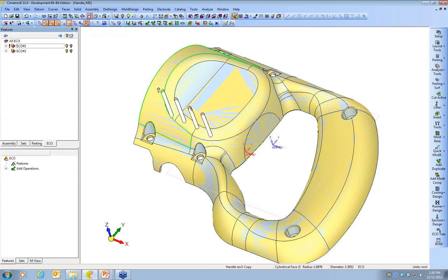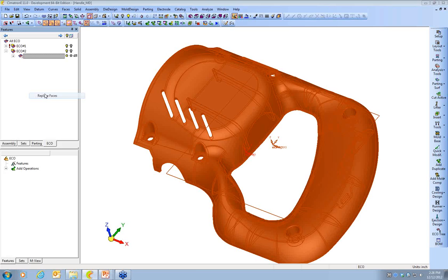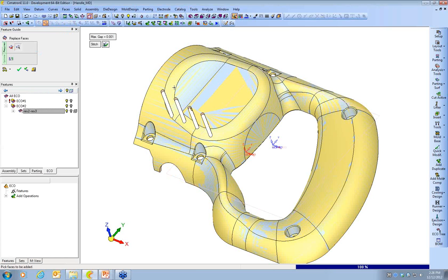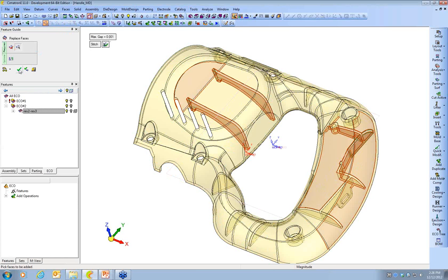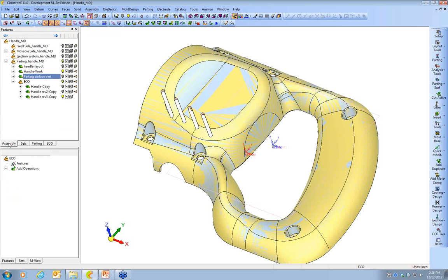So with that correct new geometry identified, we can get on with implementing this into the mold design. And this time the choice is going to be to replace faces. As the user needs to do nothing extra in this case really, we're going to confirm it. The work file was already set up to be the receiving part when we did the analysis. And replace face is merely letting us confirm the geometries that are being added and removed. So that makes the switch for us.